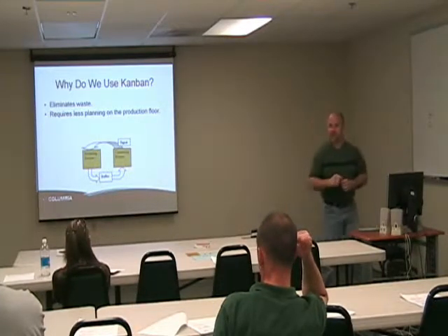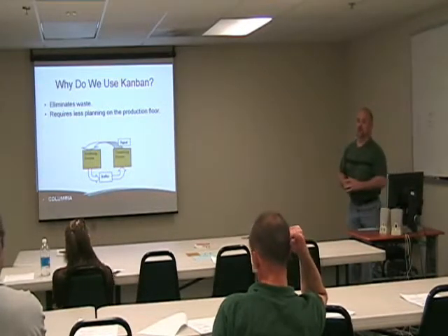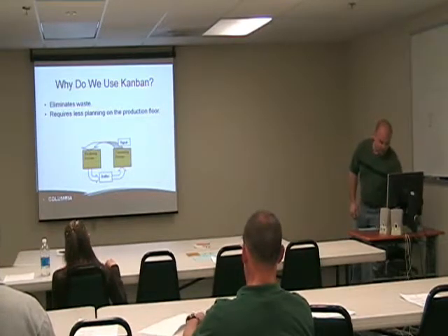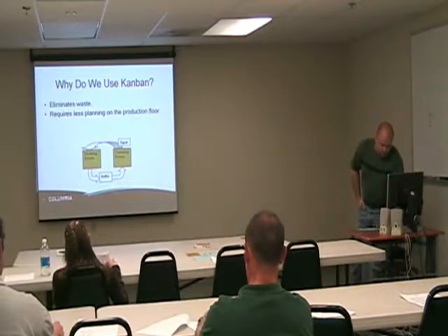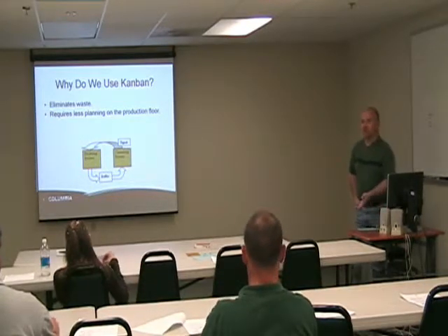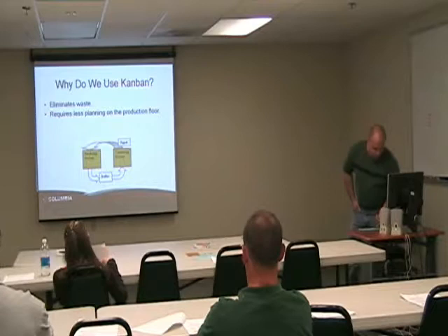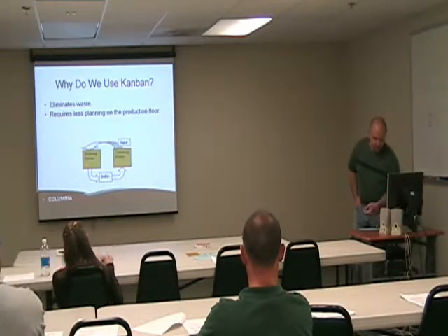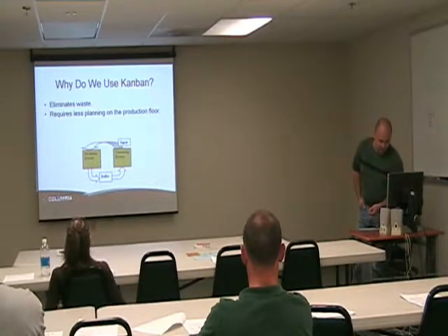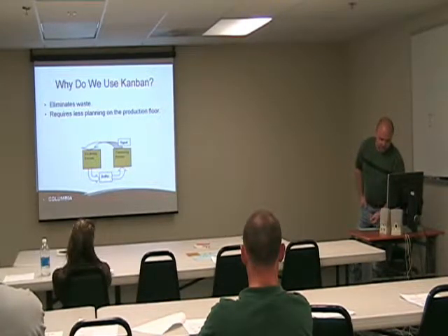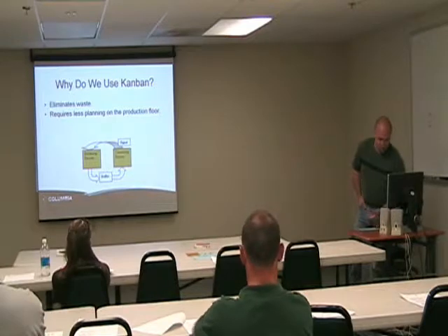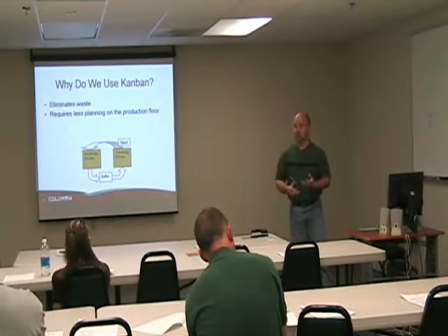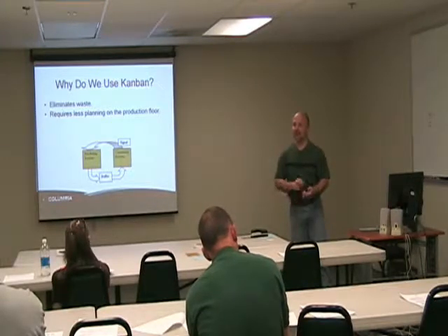5S, and there's, I think on the back page or second to last page of your handout, a breakdown of what 5S is, but I'm going to go into it here as well. First is sort, the first step in an organization. Second is set in order: organize, identify, and arrange everything in order. Shine, regular cleaning and maintenance. Standardize, make it easy to maintain. Sustain, maintaining what has been accomplished. If we do these, we can make our Kanban system also sustainable, maintainable, and easy to use.